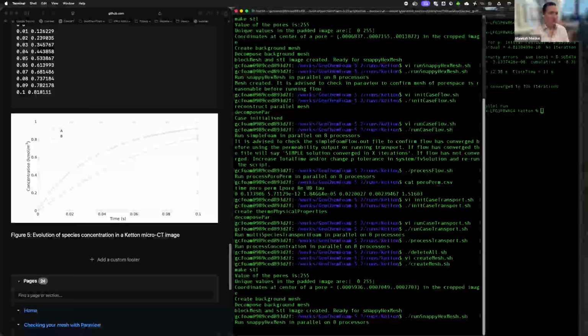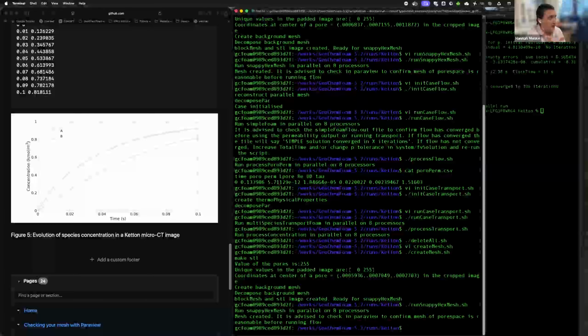What decisions? Yes, I can in X, Y, Z direction. In a case flow, I think it's in create mesh. It's in create mesh. Okay, yeah. Then you decide which is the inlet and the outlet. It's the direction 0, 1, or 2. And then we have some scripts that copy over that information into all of the different control files.